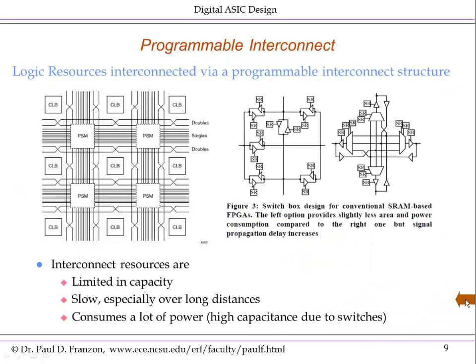So they're the logic functions. You have both general programmable logic functions in the CLBs and specific logic functions to support various high-level operations, to support clocking and I/O. Next, look at the programmable interconnect. The idea in general is associated with each CLB is a set of wires around it, and of course wires to the CLB that are not shown here, that go to a programmable switch matrix.